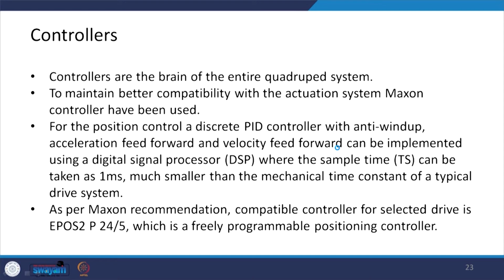And as per the Maxon recommendation, the compatible controller for the selected drive is EPOS2 P24/5, which is a freely programmable position controller which we used over here.